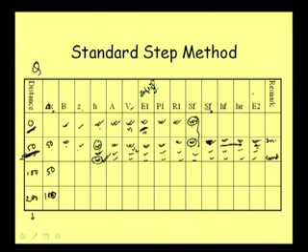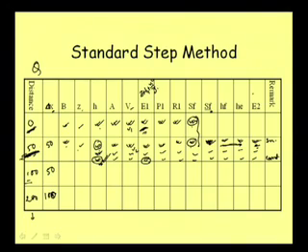So then we will go for the next 100 and follow the same procedure, and the energy E1 will take the one corresponding to the ultimate H that we got as correct, and we will keep on computing. This process will continue and then we will get the depth at different sections. These sections are already known.